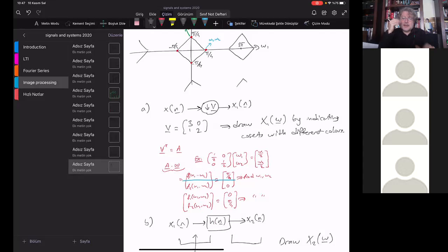In fact, there is a further research idea that is generated from here, which is still an open research topic. So you may be researching for that as your project, which you have to decide, as you may remember, which is called sparse sampling. In sparse sampling, it is not even a periodic kind of sampling, but it is just an irregular bed of nails, which samples densely at high frequency ranges and sparsely at lower frequency ranges. It's a non-uniform sampling, such that with that sparse sampling, the signal can still be reconstructed.